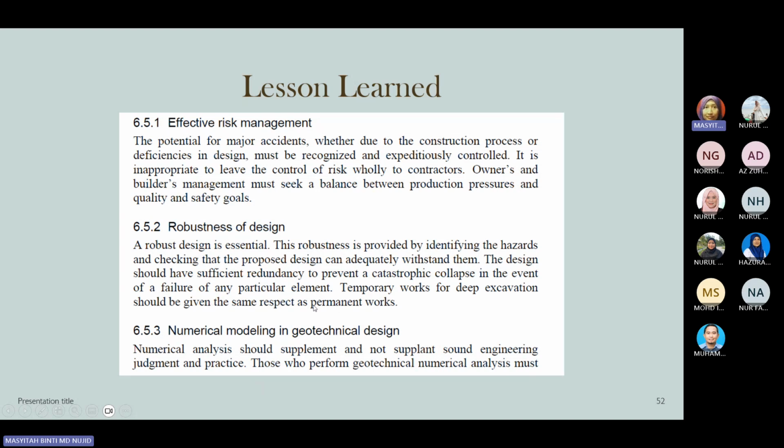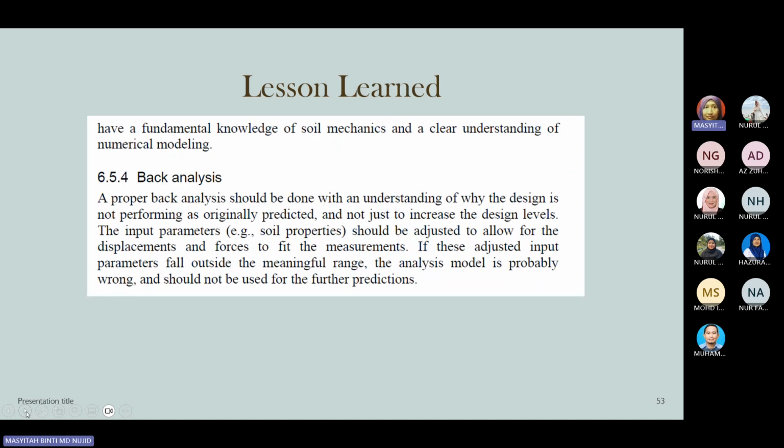And the temporary works for deep excavation should be given the same respect as permanent works. And finally, numerical analysis should supplement and not supplant sound engineering judgment and practice. So those who perform geotechnical analysis must be capable of validating and verifying the results. A proper back analysis should be done with an understanding of why the design is not performing as originally predicted, and not just to increase the design levels. For example, the input parameters should be adjusted to allow the displacement and forces to fit the measurements.